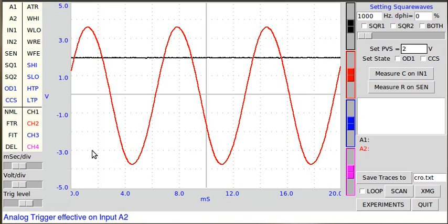There are other features, like if you want to measure the frequency of this AC waveform, you can do it by a mathematical fit. Drag channel 2 to fit. So this compares this with the sine wave and says the voltage is this and frequency is around 150 Hertz.